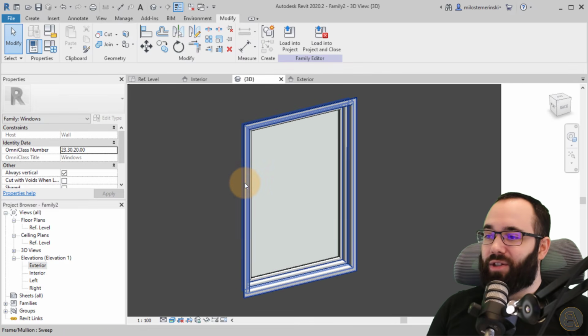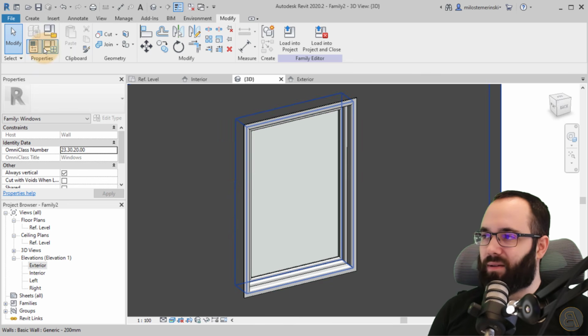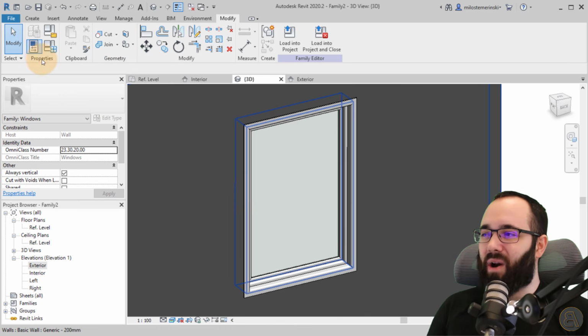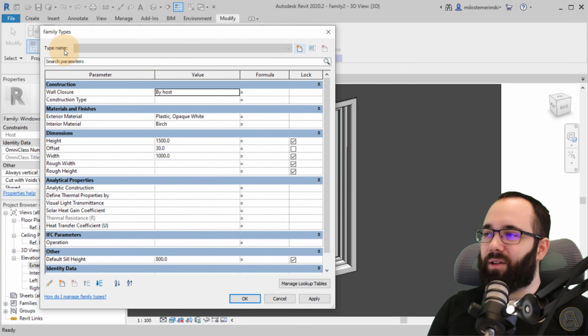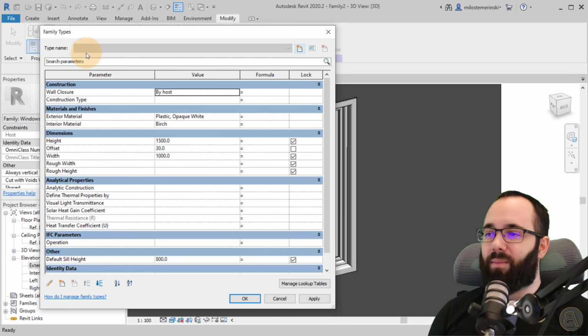And now let's just set up the family types, and we're almost done. So this video is going to be 30 minutes long, which is quite long. So let's go here to the properties panel, go to family types. And then you'll see that we don't really have any family types here. So the family types are basically when you open up the family inside of a project, you know how you have the option to set up different sizes? Well, this is it. This is that.